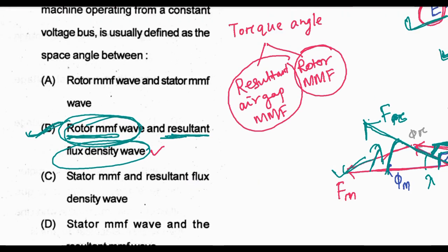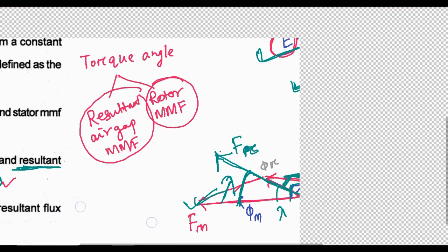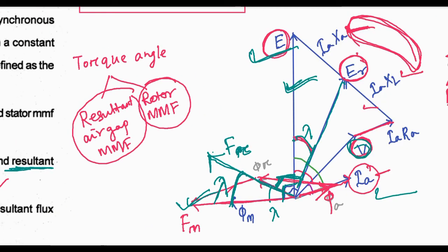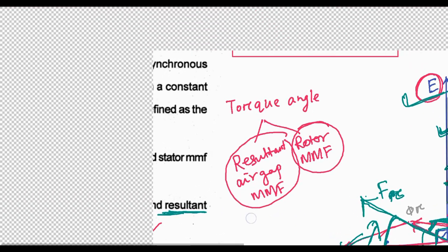And one thing, the difference between load angle and torque angle: this one is the load angle, this one is the torque angle. So what is the difference? The difference is the leakage reactance drop. So here is the answer. Next question.